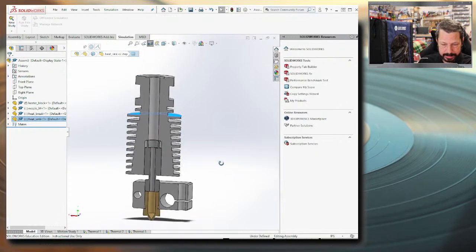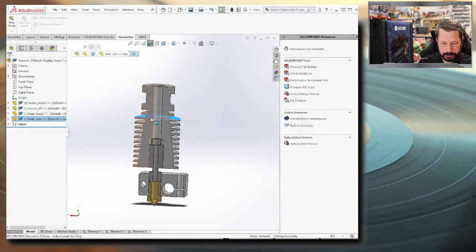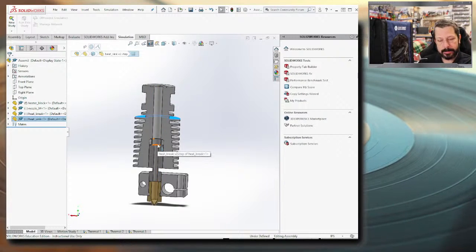And so you can kind of see where the Bowden tube ends right here in this nozzle. Some people get confused. Well, that's not all metal. The Bowden tube goes down in there. That's true, but the Bowden tube ends at a point where the heat at that point should be below the glass transition temperature of your filament.